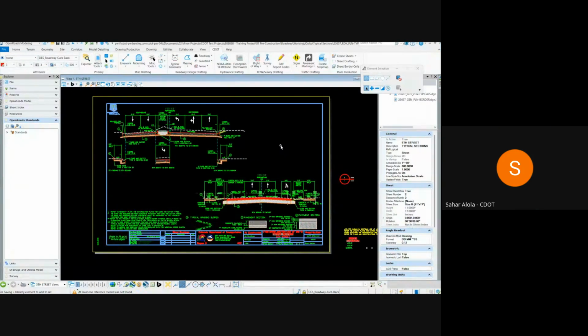I just want to add a quick comment here. I know on a given project, we do existing typical section and proposed typical section, and in the past we used to have the quality assurance document when we tell everyone, we encourage everyone to cut cross section of the existing, like you receive the existing and you have your terrain, you receive geometry existing, and then you cut your cross section and you actually look and see what is pavement and roadway doing with the existing surrounding and stuff before you start.